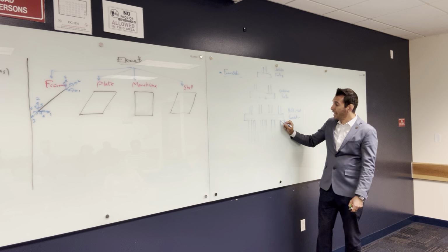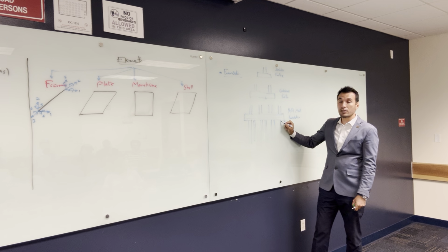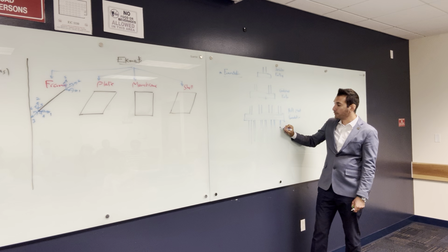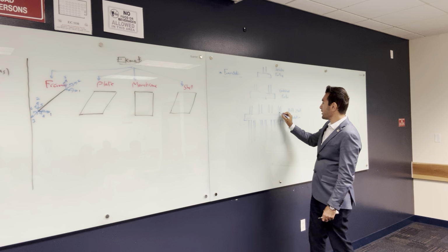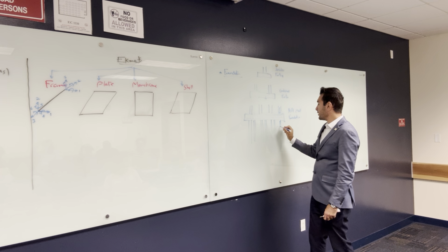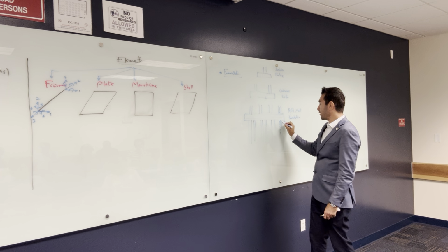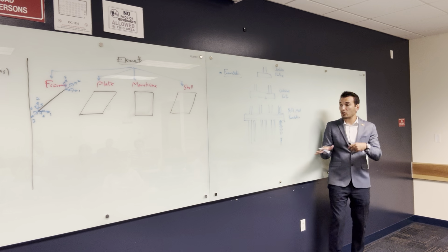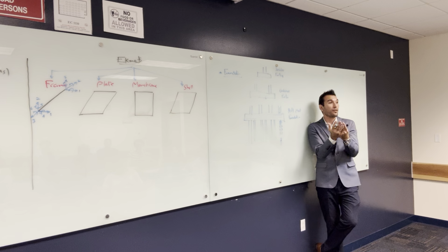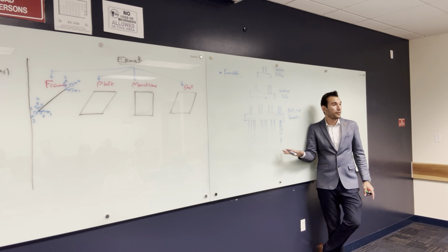So we take the load, and the load basically gets distributed into friction on the pile, something like this. Basically, the load is coming from here like this, so the pile is going to have some friction, like this, and then at the tip here, there is a reaction. So the load that comes from the structure is getting distributed on the side of the pile and at the tip of the pile, at the base of the pile, something like this.